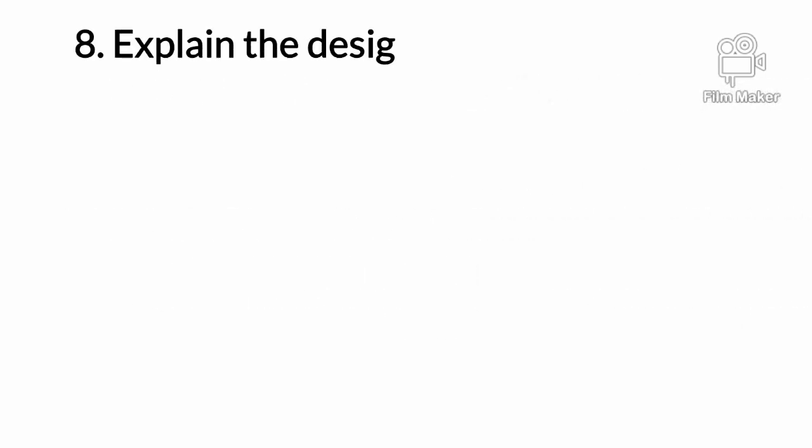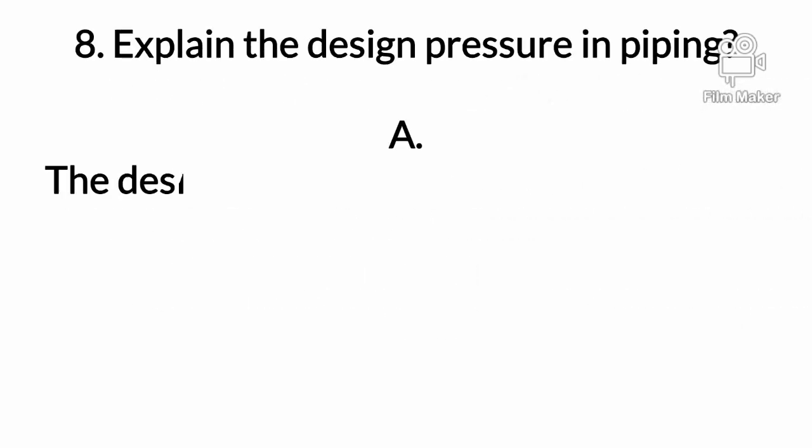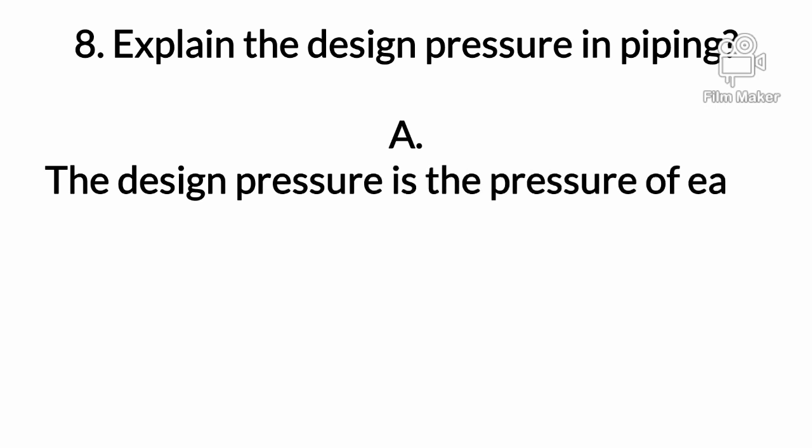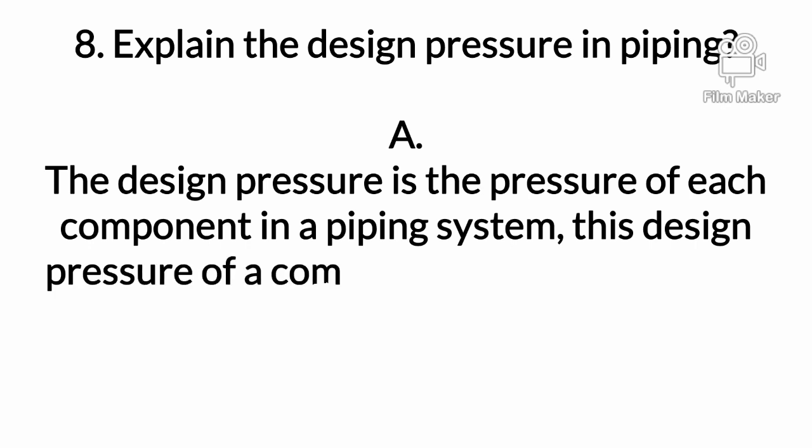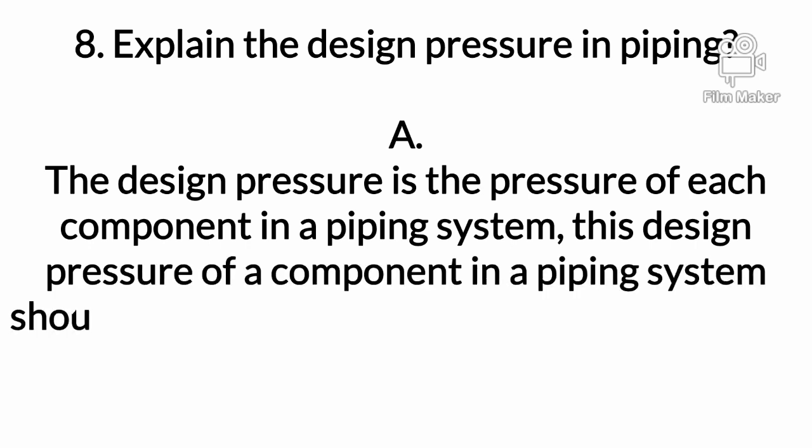8. Explain the design pressure in piping. A. The design pressure is the pressure of each component in a piping system. The design pressure of a component in a piping system should not be less than the highest pressure which could occur during the service.